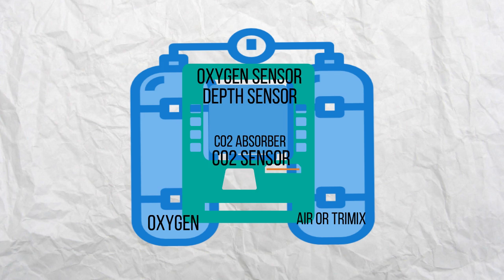So within a rebreather you have an oxygen sensor, and it will also always have a way of knowing what depth you're at, and using the percentage of oxygen in the breathing loop and knowing its depth, the rebreather will always know what the partial pressure of oxygen the diver is being exposed to, and that avoids oxygen toxicity.